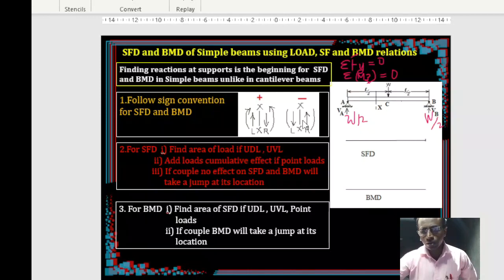And vice versa. When you are on the right of the section, downwards are negative and upwards are positive. As far as bending moment is concerned, anti-clockwise moments are taken negative when you are on the right of the section.